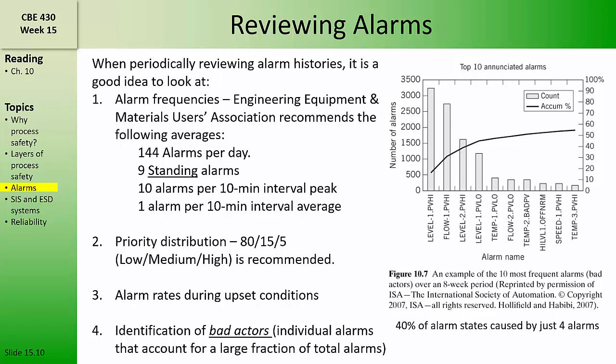Occasionally, operating conditions lead to multiple alarms simultaneously. No more than 10 alarms should have to be dealt with within a 10-minute interval at a peak alarm condition. And on average, operators should have to deal with only 1 alarm per 10-minute time interval.